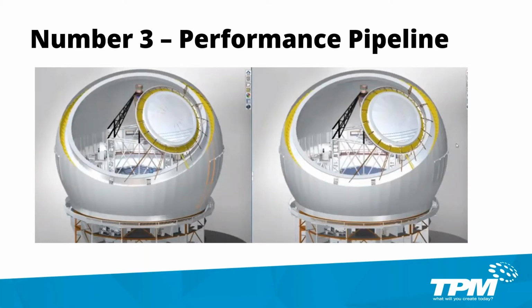Now, this one, number 3, the performance pipeline. The performance pipeline or enhanced graphics option was introduced in beta mode in 2019, and then it was cast as a default option in 2020 and beyond. This one happens mostly under the hood, but this allows SOLIDWORKS to scale relative to the power of your graphics card and represents a noticeable performance boost to anyone who uses it. Let's take a look, and then I'll tell you guys how to turn this one on.